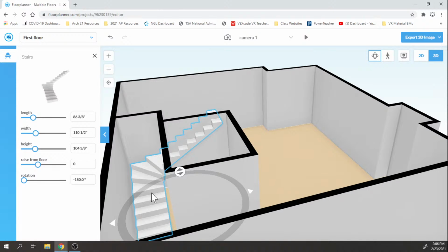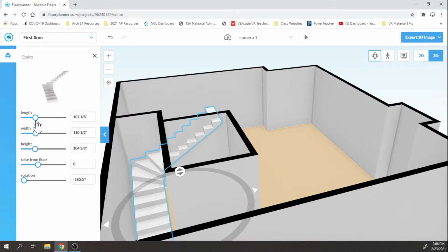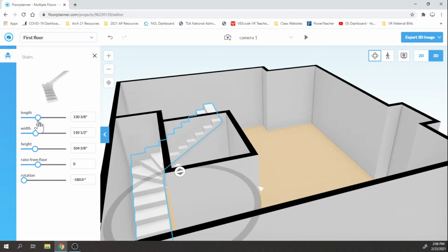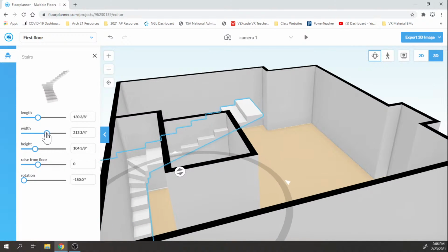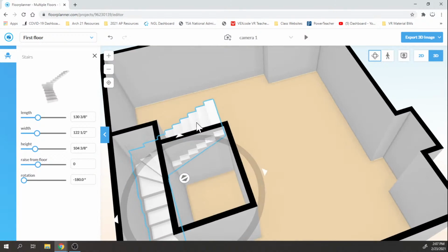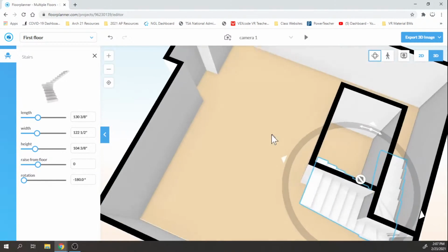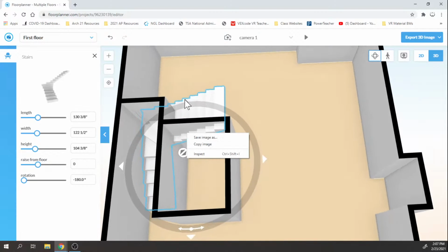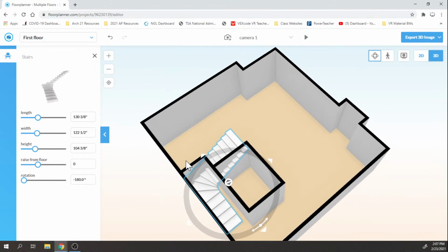And if I click on this, I have how wide the stairs are. Don't be confused by length. Then we have this direction. That's how deep the stairs go back. But you can't independently change the specific geometry of just one leg of this angled stairwell.